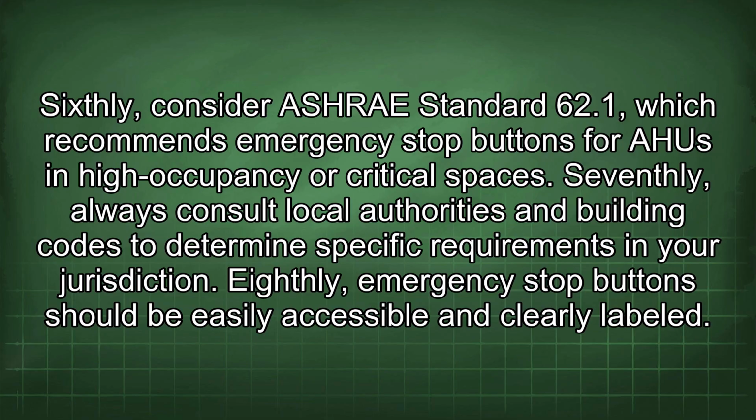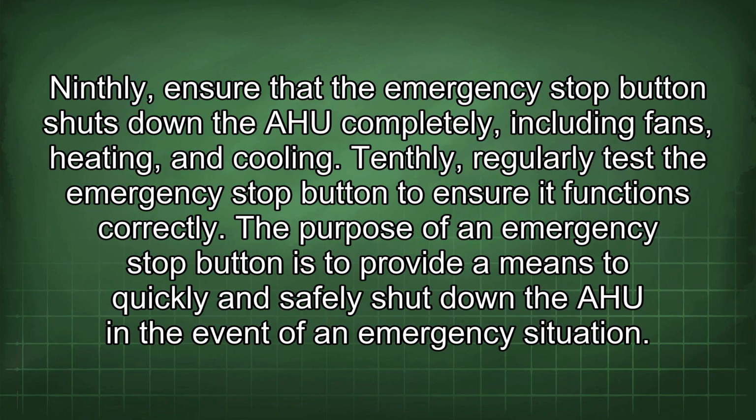Eighthly, emergency stop buttons should be easily accessible and clearly labeled. Ninthly, ensure that the emergency stop button shuts down the AHU completely, including fans, heating, and cooling. Tenthly, regularly test the emergency stop button to ensure it functions correctly.